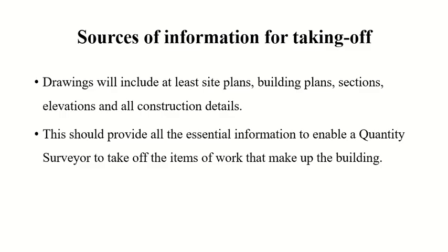Site plan is before we build something, the building plan after we check everything is correct. Anybody else? The site plan focuses on the road and the whole area, but the building plan focuses on units. Yes, you can have a site plan even before constructing the building or after constructing it as well. But the details shown in the site plan are not the building rooms and foundations. The site is usually bigger than this. And then you have sections, elevations, and all construction details, including the specifications as well.